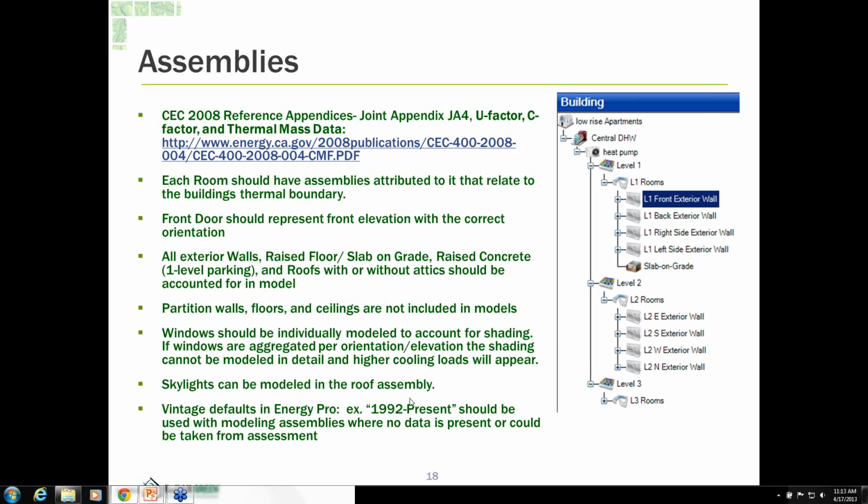I have one question: I always get an error with more than 6 bedrooms in a home. Is there a particular reason? So the error messages, you can ignore that unless it stops you. There are 2 types of error messages in Energy Pro: one that actually stops you from running calculations, and one that just says, hey, you have more bedrooms than what's typically found in a residential building, are you sure this is correct? But it'll still run the calculations. It's just kind of like a warning.